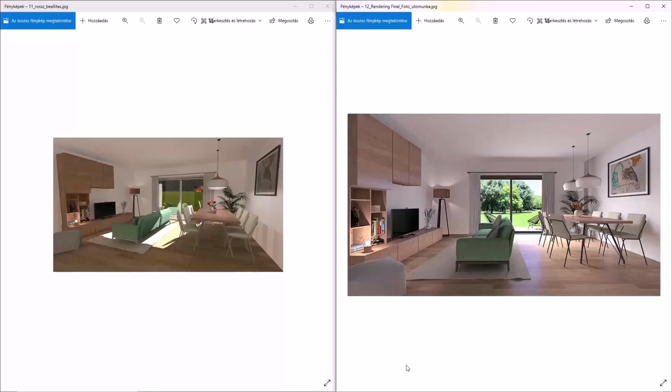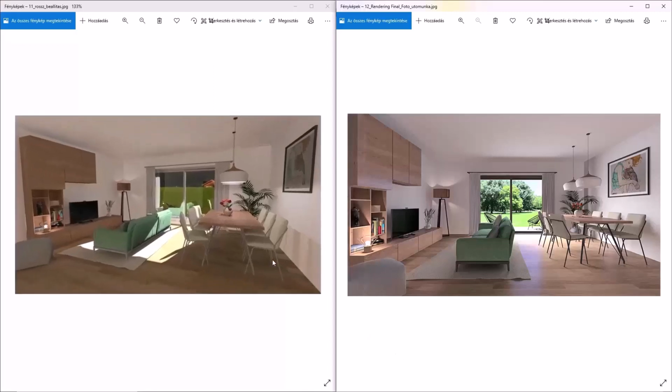The first is to set the perspective. In the first image, I have chosen a diagonal perspective setting. I wanted to get as much of the scene as possible, but I could only achieve an insignificant scene. The camera and the subject are not at the same height, so the walls are tilted and not parallel to each other. In the second picture, the perspective is completely perpendicular to the opposite wall. The walls are parallel and the camera and the subject are at the same height. This value is ideally between 1000 mm and 1400 mm. Here it is set to 1100 mm.